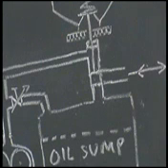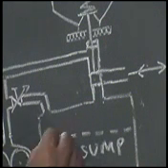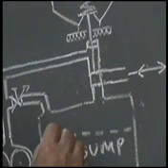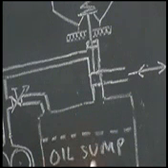So if we do not give a certain amount of empty space in the sump, the increasing volume due to the increasing temperature will affect the proper functioning of the governor.